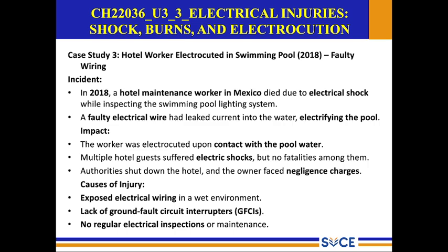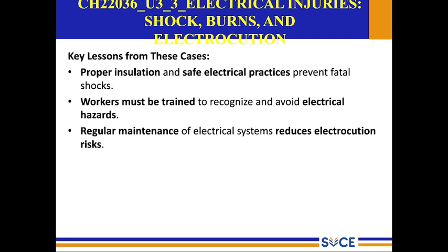The cause of injury comes in three different types. Number one is exposed electrical wiring in a wet environment. Then lack of ground fault circuit interrupters, GFCI. And no regular electrical inspections or maintenance. That also leads to such incidents.